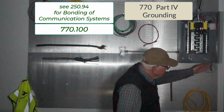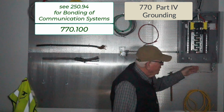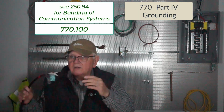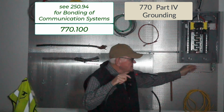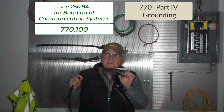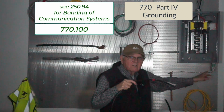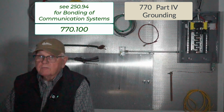Then I have what? 1, 2, 3, 4, 5, 6 terminals where I can bring in my intersystem bonding conductors, where I can bring in my bonding jumper from my metal sheath and attach that bonding jumper here to my intersystem bonding termination. Then what does that do? That then places this metal sheath at the same potential as my grounding electrode conductor, the earth and ground that I'm standing on. So that's a pretty important connection.